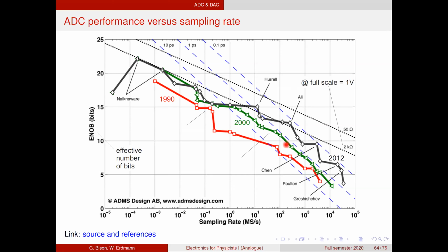these noise calculations, and the same square root law that you find if you average a signal. So if you take the 10 million points you get per second here, and you average 100 points, you reduce your sampling rate to 100 kilohertz. So here, and then you increase the resolution correspondingly by a factor 10.